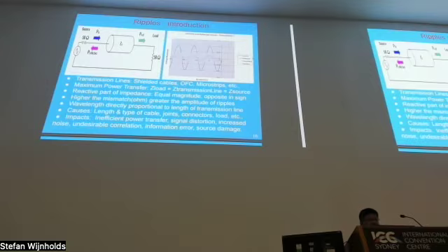Next, the last one, is the ripples in the band. Ripples are mainly due to mismatch in the transmission line, mismatch in the impedance between source, transmission line and load. This mismatch will cause reflections. The resistive parts should be equal, meaning if it is a 50 ohm load, then the transmission line should also have 50 ohm and the source should also have 50. So all should be matched.